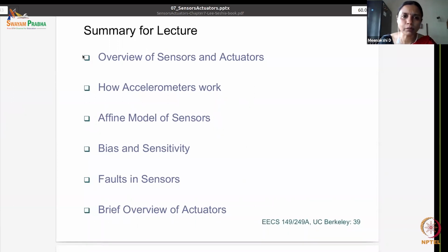When it comes to non-volatile memory, as I told you, it means that it's a memory that preserves, retains, and stores content even when power goes off. These are the kinds of non-volatile memories. There is erasable, programmable, read-only memory, which is an old one. There is electrically erasable, programmable, read-only memory. There's flash memory. There are also disk drives. We clearly cannot rely on disk drives for embedded systems because they won't meet our real-time constraints.